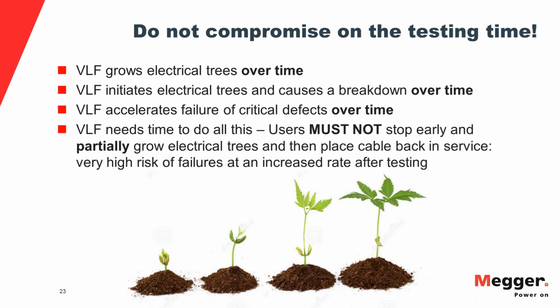So they were like, oh, VLF test is bad for the cable. And then further investigation, asking a simple question. So how long did you test the cable? And they said, oh yeah, we just did 10 minutes and then we stopped because the cable would hold the voltage. Well, this is exactly wrong, because you started the acceleration process of the electrical trees.